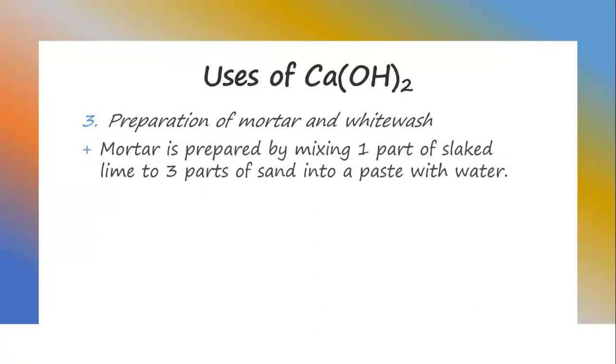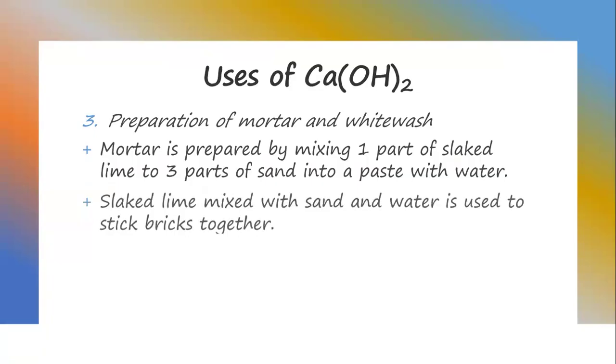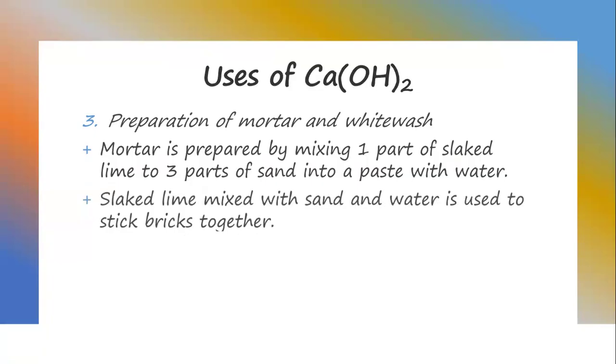The mortar is prepared by mixing 1 part of slaked lime to 3 parts of sand into a paste with water. Slaked lime mixed with sand and water is used in sticking bricks together.